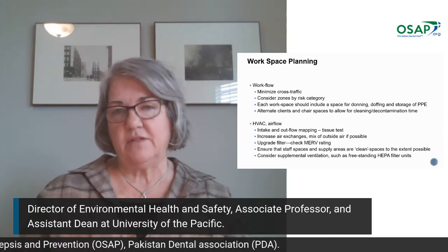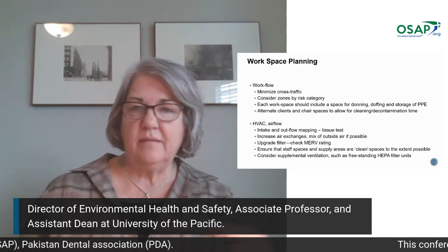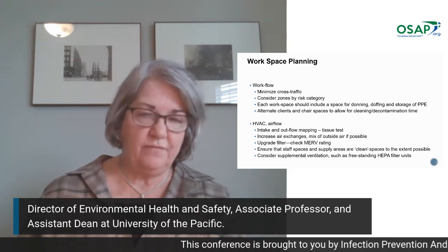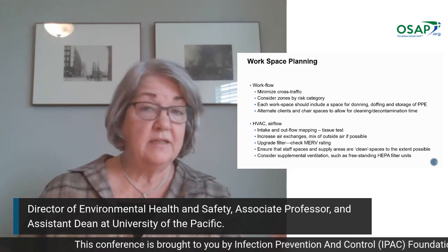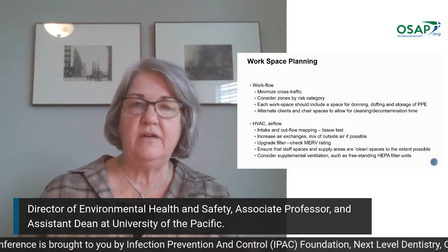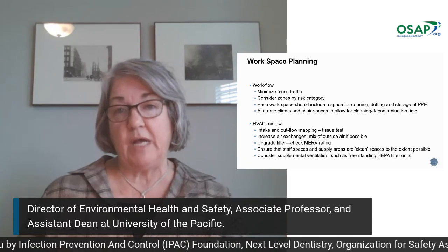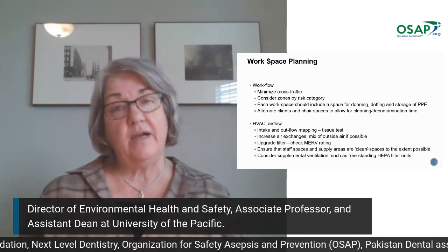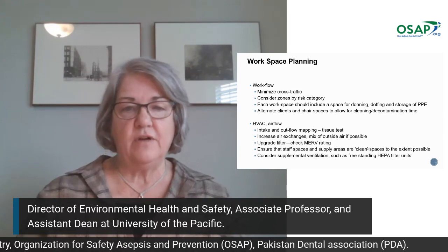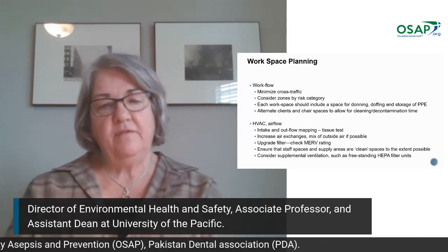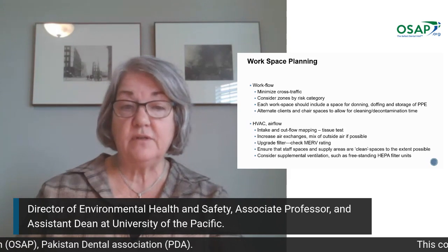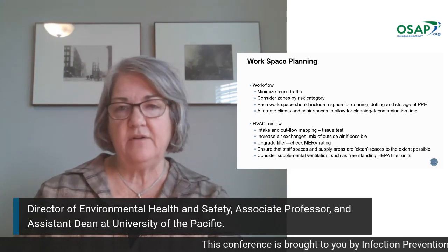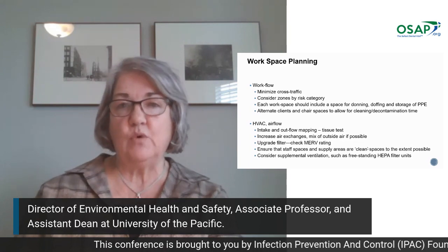Or if you're in a smaller setting where there isn't necessarily ventilation pushing air out, there's only ventilation air coming in, such as in an air conditioning unit or a heater, you might want to position, if possible, the patient near an open window. Open windows will also help increase your airflow. If you can upgrade your filter, that would also be helpful. There are different ratings for filters, and the higher the number, it's called a MERV, the more efficient that filter is.